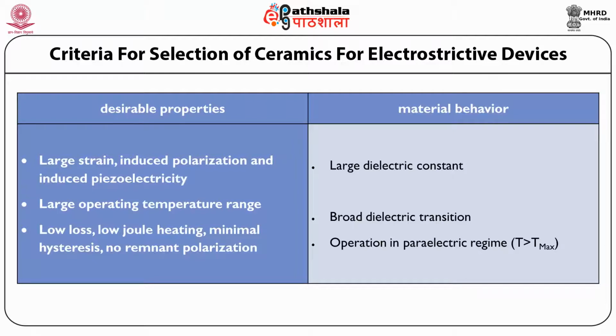And the material behavior properties for the selection are: large dielectric constant, broad dielectric transition, operation in the paraelectric regime, that is T greater than Tmax.